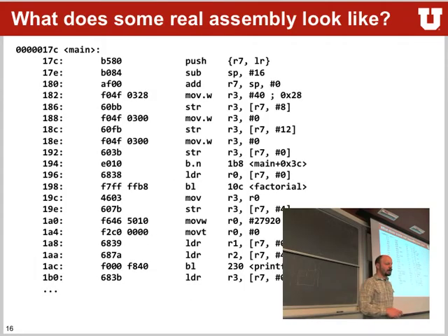All right. So what's happening here? Well, the first instruction is a PUSH {R7, LR}. Anybody know what a push would do, or an idea of what a push would do? Store something, right? You probably have heard of push and pop from C programming, that's when you put stuff onto the stack and take it off the stack. That's exactly what this instruction is doing. It's pushing R7 and the link register onto the stack.